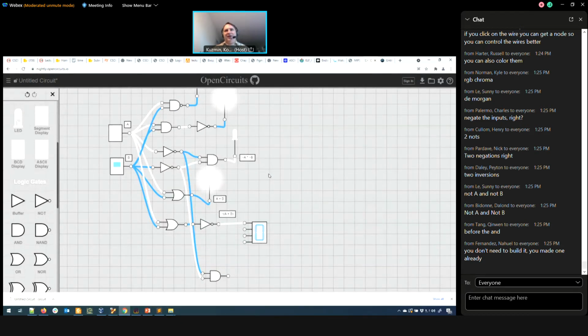In a real electrical engineering design, you would have to be concerned about the load, because every integrated circuit, every actual electronic device has a loading capacity, so you cannot connect infinitely many loads to any output. There is a maximum drawing current capacity, but for logical design we just ignore it, so you can use a particular output as many times as you want. Okay, all right, so that's that.